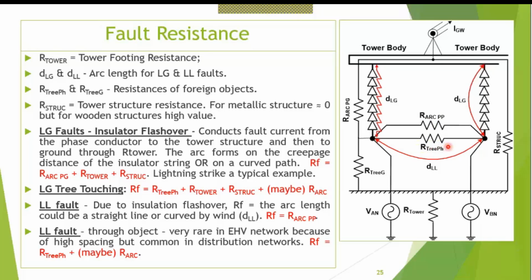So it is not that phase-to-phase faults should incorporate arc resistances only. There is a possibility that it might encounter higher resistances. So it's better to use a little bit more. Do not take arc resistance as the only resistance parameter for phase-to-phase faults. Okay, so this is what is given in these two paragraphs.